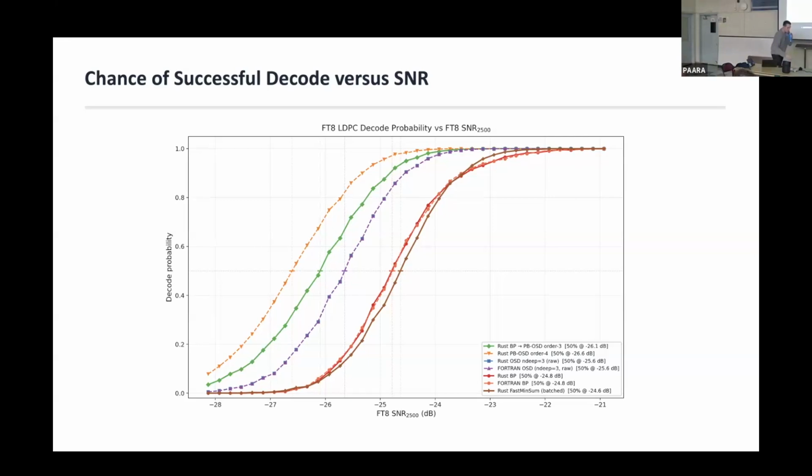Do the metrics align? If you're doing a good fast decoder, does that get you the other metrics you need at the same time? Yeah. The way it works under the hood is you could keep everything else fixed and just replace this decode method. And when WSJT-X finds a decode, you have the advantage of knowing the complete waveform, not just the fixed tones that are played there.